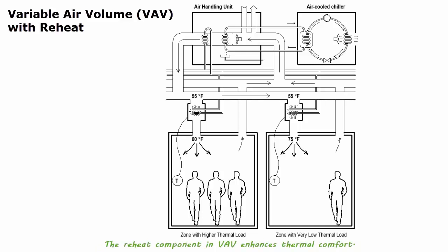The reheat component in VAV enhances thermal comfort, as it is only used when and where it's needed. The energy penalty for reheat is considered reasonable. However, it certainly increases installation and operation costs compared to VAV without reheat.